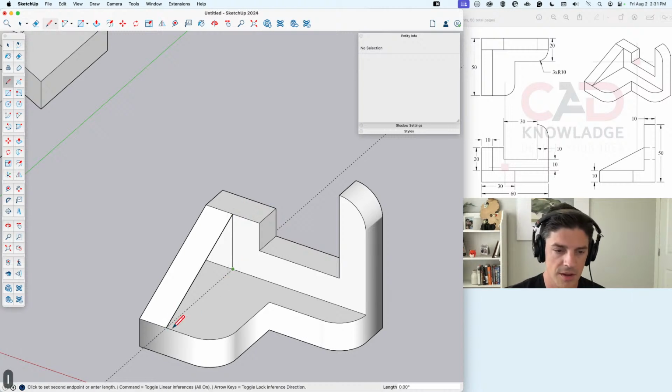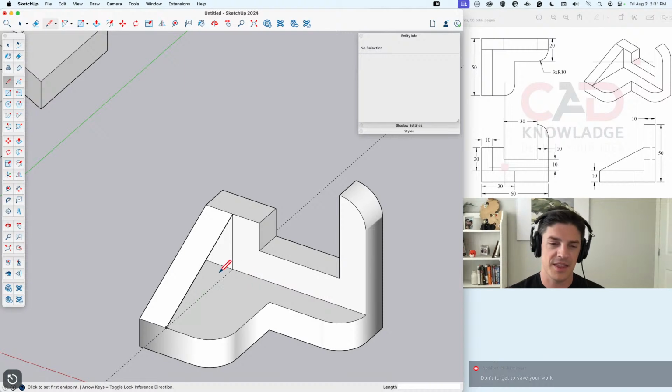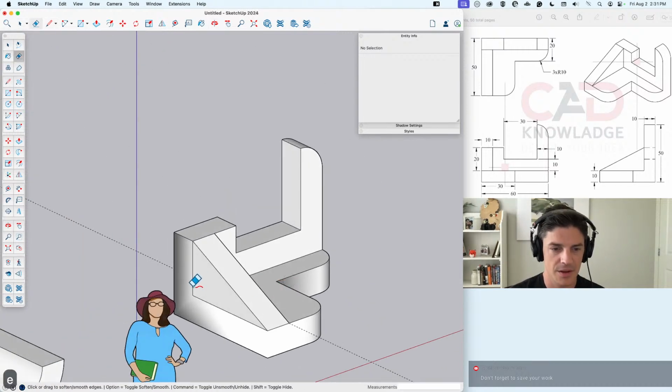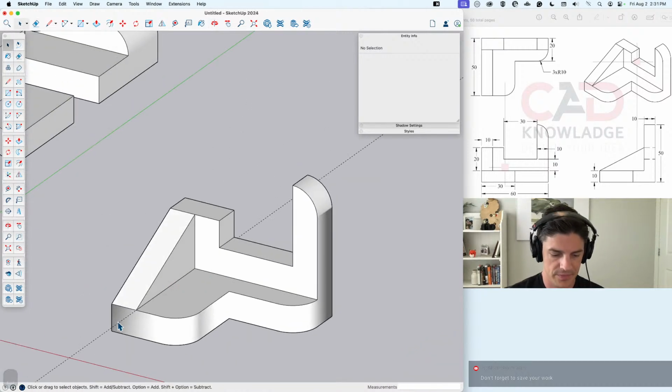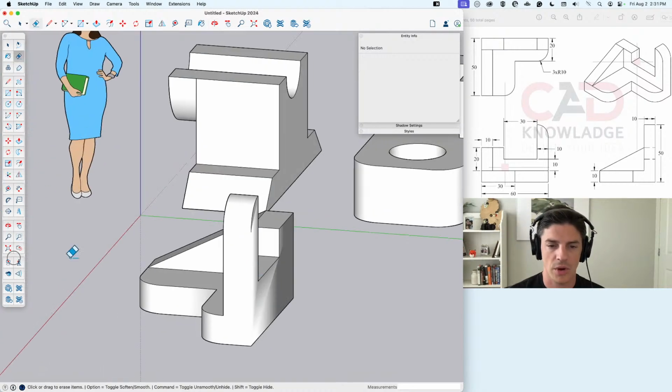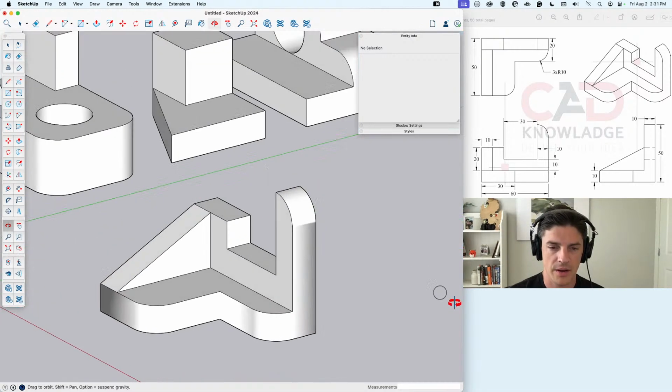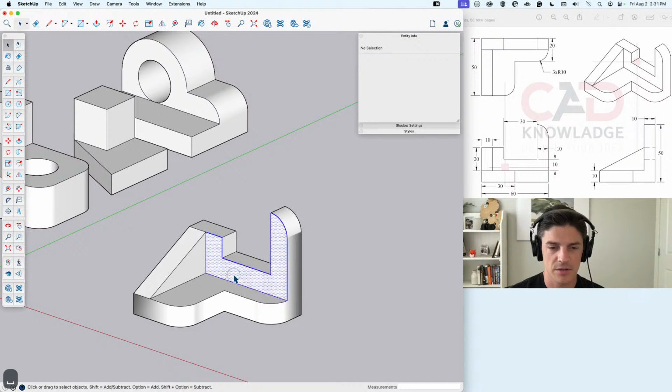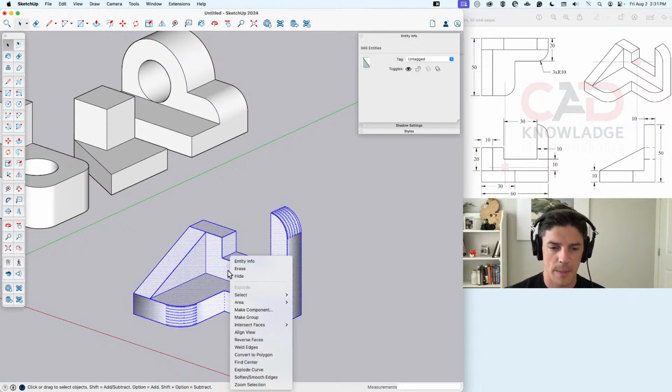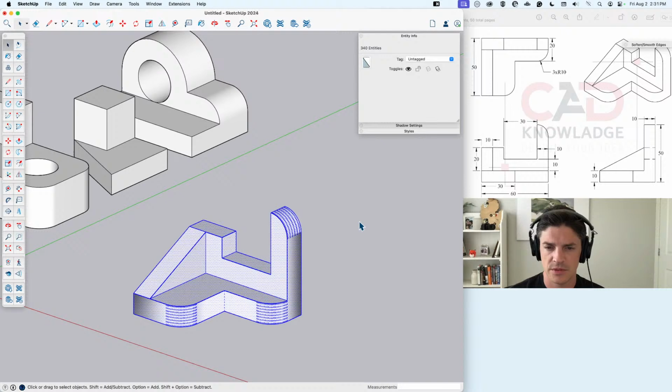One thing about using guides is sometimes I think this is a line, and I'm like, why is my face not closing? And then there's no line there. Do you have a shortcut for toggling guides on and off? Do I? I don't think I do. Like delete guides or hide guides, because you can make them visible or hide them. No, I don't currently have that set up, but it probably would be a smart thing to do. I'm actually going to change this, soften and smooth.